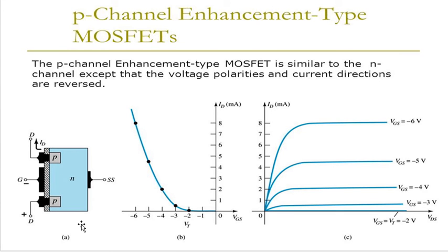So both at the drain and source we have the P-type material and the channel is not present. So in this type of MOSFET, which is a P-type MOSFET, when you provide a positive signal like for an N-type MOSFET, this will not turn on. Here you have to provide a negative gate signal to turn it on.